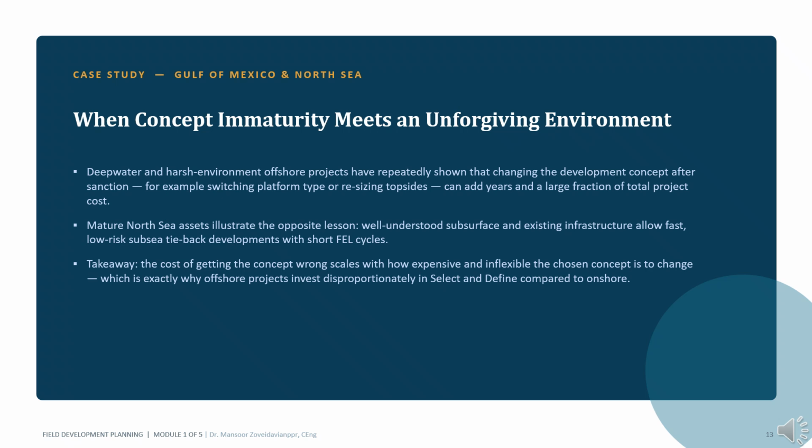On the other hand, many mature North Sea developments illustrate the benefits of infrastructure-led development. Existing facilities, known reservoir behavior, and established export routes allow relatively simple tieback developments to be executed with lower risk and shorter front-end cycles. The broader lesson extends beyond these two regions. The cost of making a mistake is directly related to how difficult and expensive it is to change the selected concept. This is why offshore projects typically invest more effort in select and define than comparable onshore projects. The less flexibility a project has after sanction, the more important concept maturity becomes before sanction.